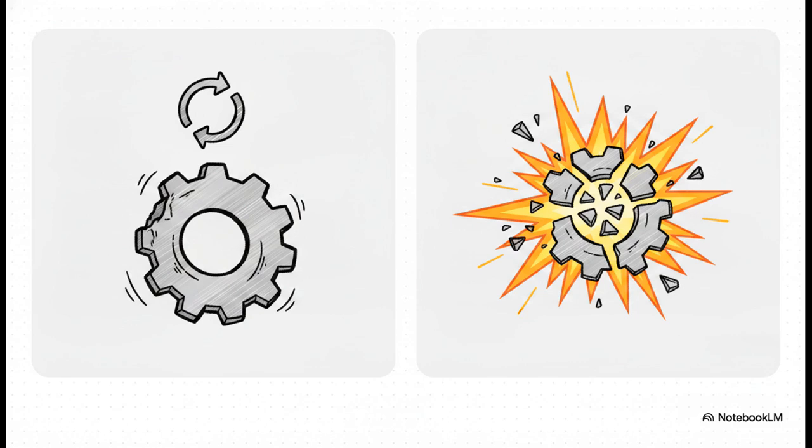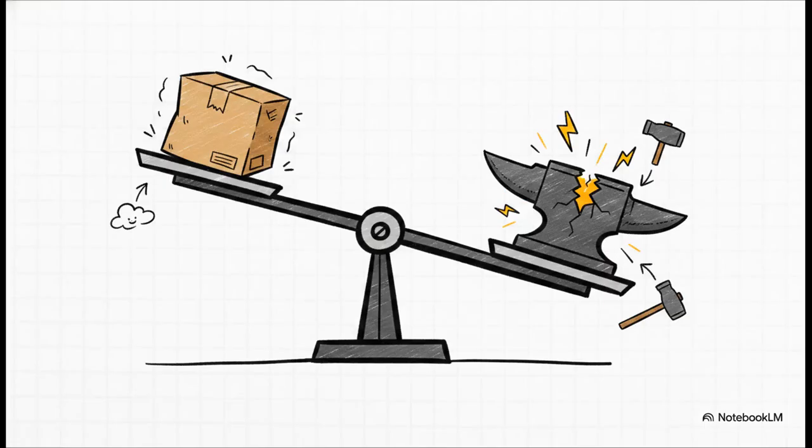However, in a hard real-time system, if results are not produced strictly on time, it is considered a complete and utter system failure. Going back to our car brakes example, if they failed to deploy before the deadline, that is a total, potentially fatal failure. Just to cement that knowledge in your minds, soft real-time means degraded operation when late, while hard real-time means complete system failure. Please recognize this difference. A very common student pitfall is failing to articulate just how severe missing a hard deadline actually is. You absolutely must be able to define this distinction clearly.